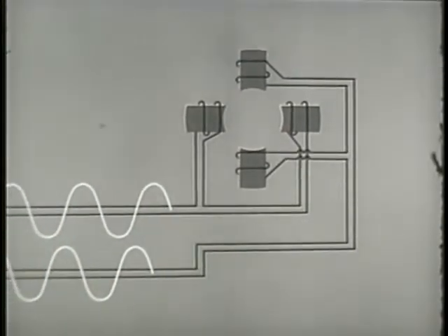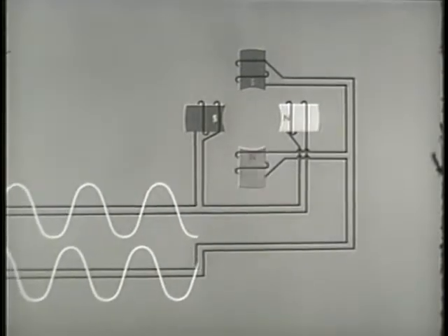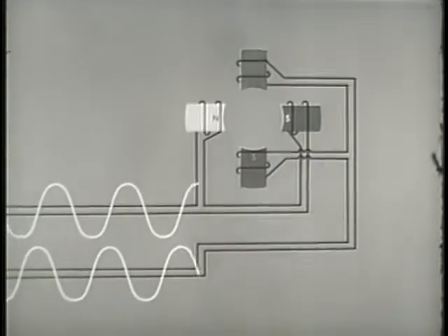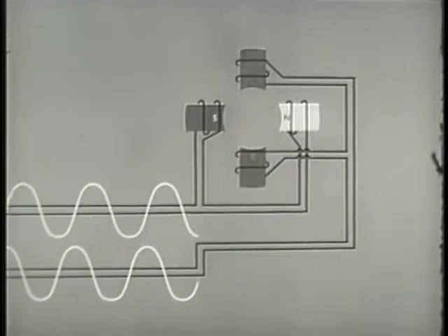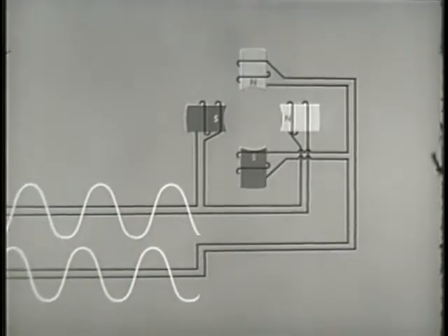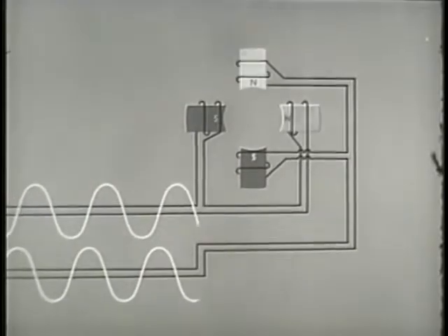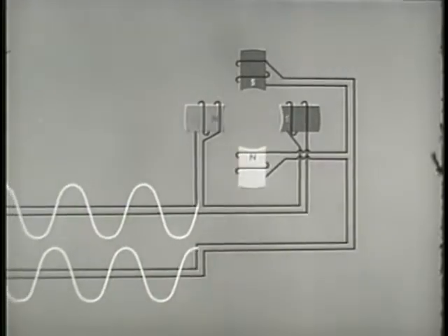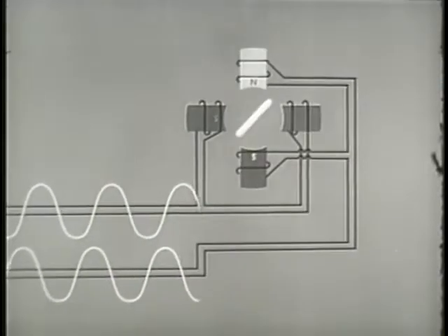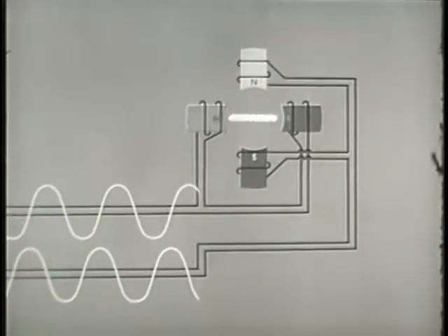Just as in three-phase motors, the phase difference is used here to energize the field poles progressively, thus causing electrical rotation of the magnetic field. As in all induction motors, electrical rotation of the magnetic field is a primary objective. Again, the rotor turns in the same direction as the magnetic field, but at a slightly slower speed.